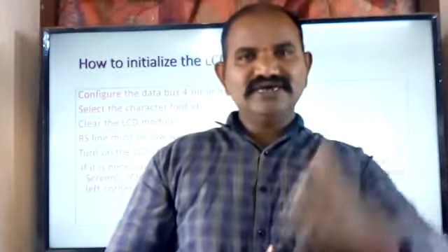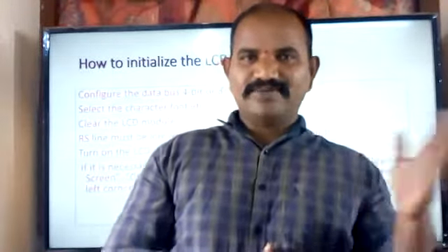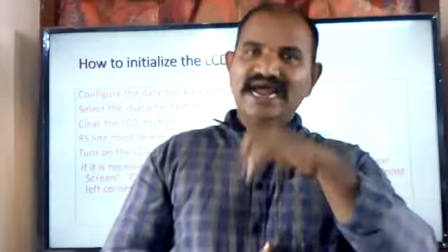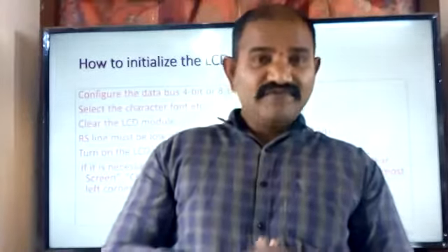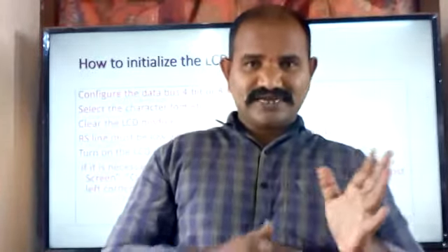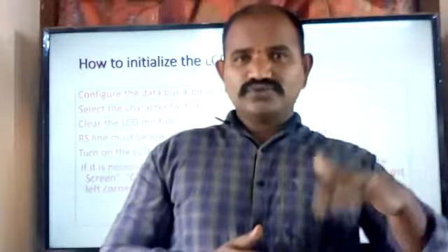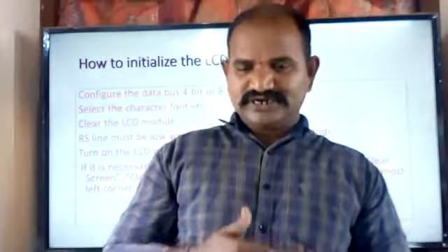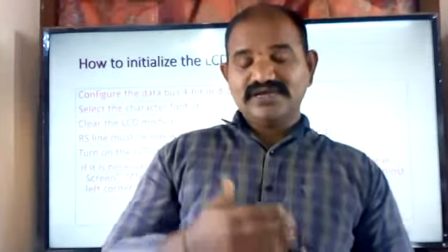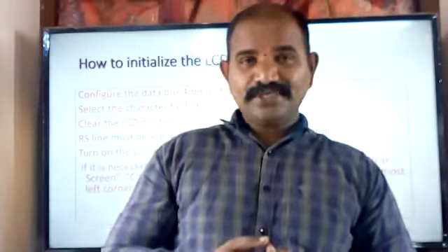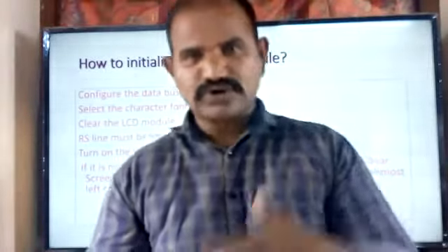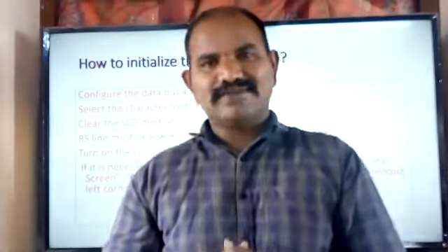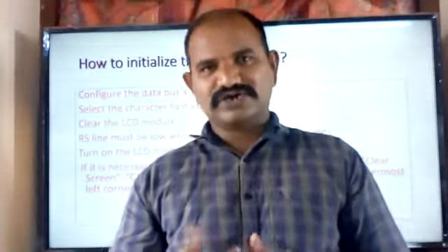You are supposed to send sequential command words from the microcontroller to the LCD module. And if you want to know those command words, you may use the data sheet of the LCD display, or any microcontroller textbook that covers this interfacing. From there you can get the command words, and see which command word does what kind of operation.